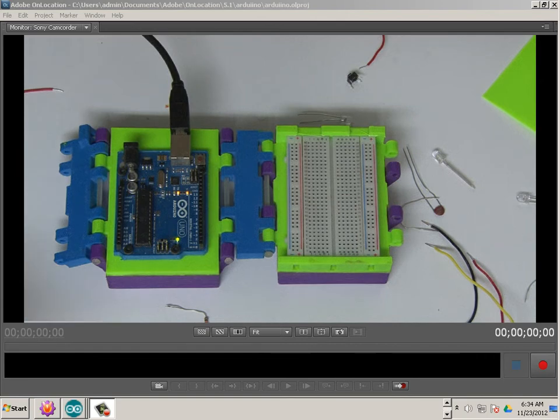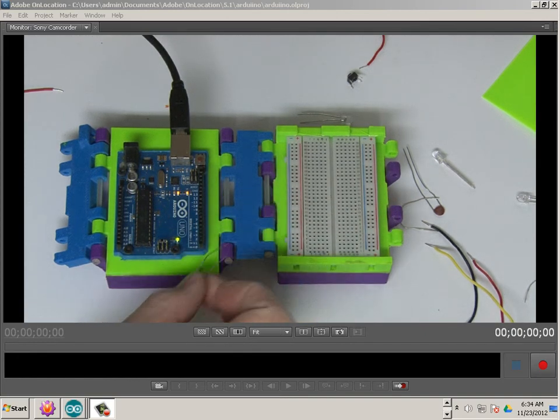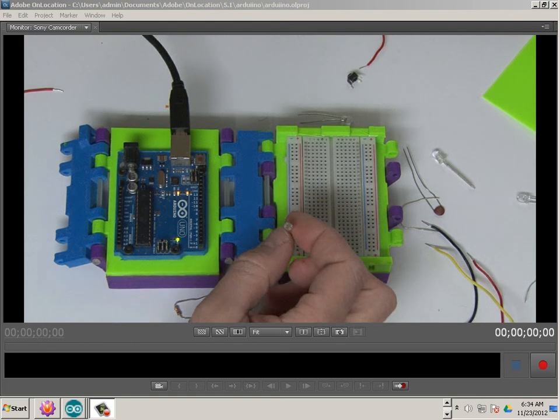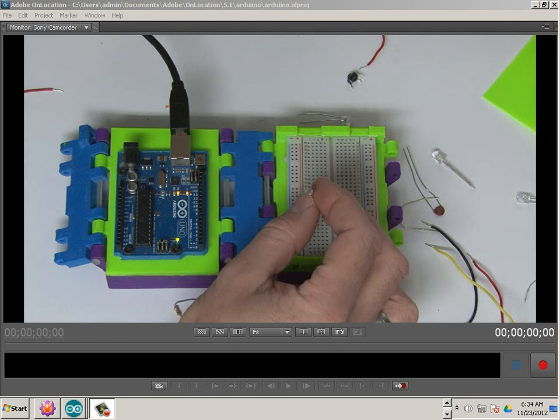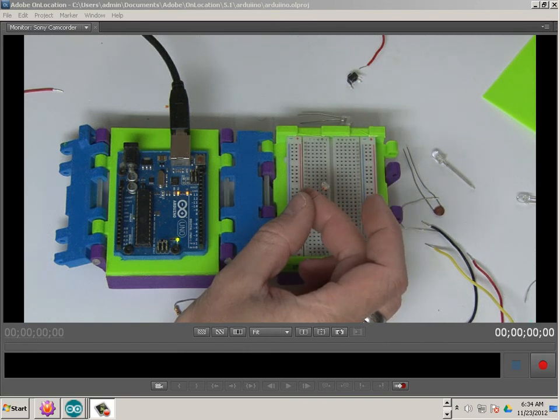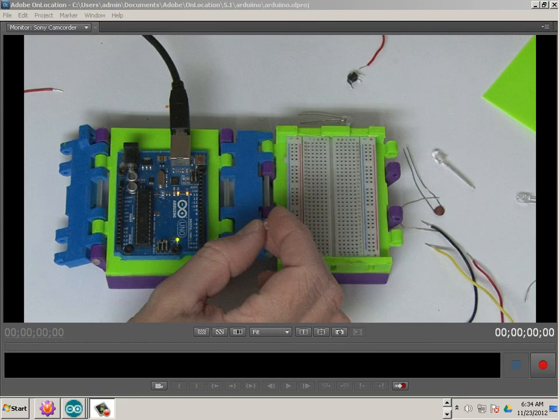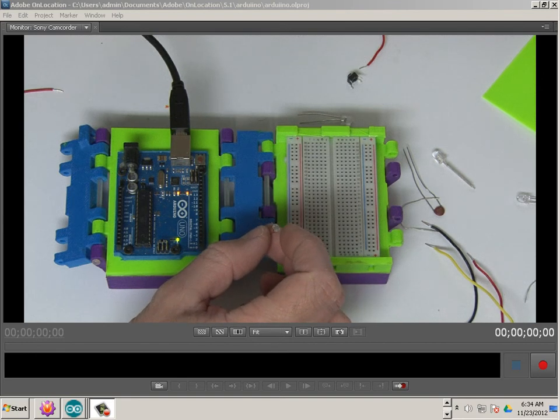Now what does it do? Well, a photoresistor is just a very fancy resistor. A resistor has a very set value. This one bases itself on the change of light. So I can cover the sensor up and a change would occur, and then let go of it and a new change would occur. Our goal here is to get as clean data as we can first before we start using it as a sensor to make an event happen.